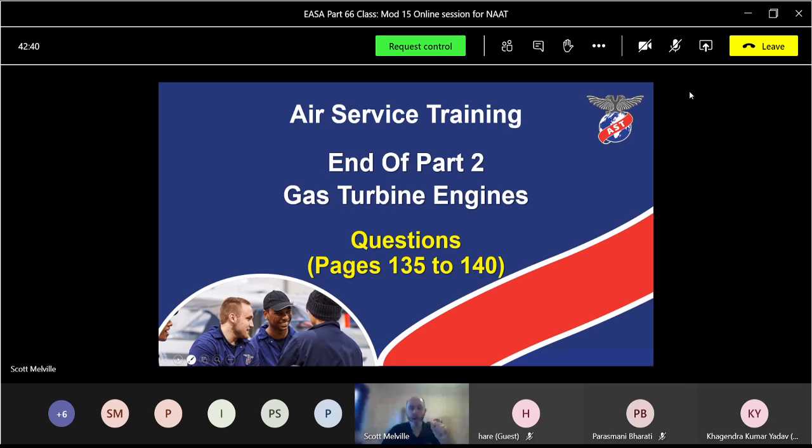And there will always be a little gap in the throttle control, which we call the throttle bounce. So we hit maximum, we get a little bounce, yeah? That's what's called throttle bounce. That's ensuring that we've got full contact with the maximum stop in the engine. So that gives confidence to the pilot that he is attaining full throttle position once you've set it all up. And I said before, you must have a duplicate check to ensure it is set up correctly.